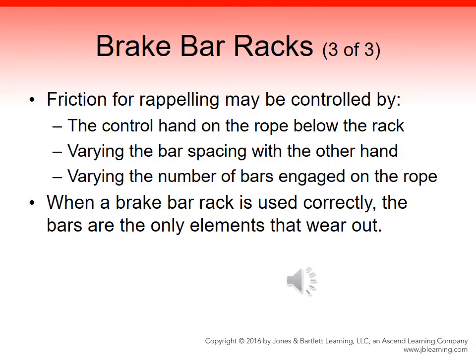In the most common configuration, the rack is arranged with a 1-inch diameter top bar. On J racks, this top bar may be grooved to keep the rope in the middle of the bars as it runs through the device. On a U rack, the second bar down is often grooved. The remainder of the rack usually is filled out with 5 aluminum bars, each 7/8 inch in diameter.